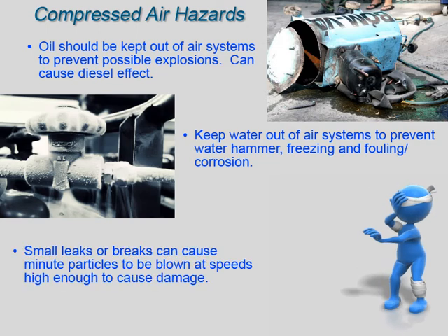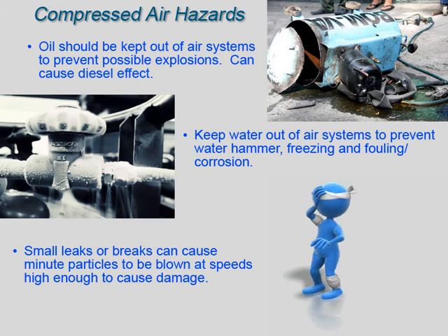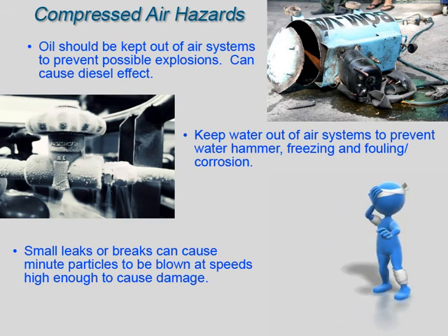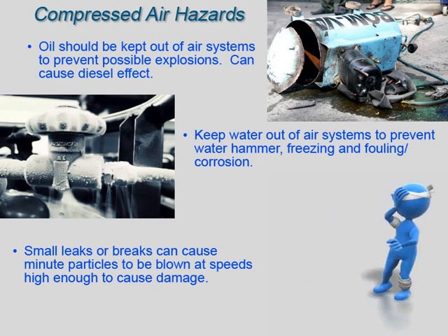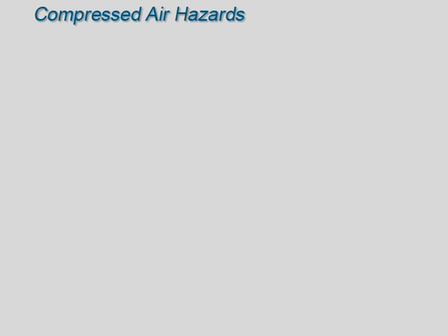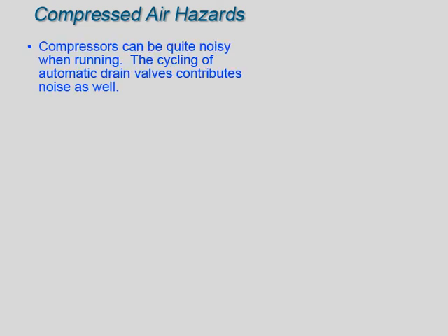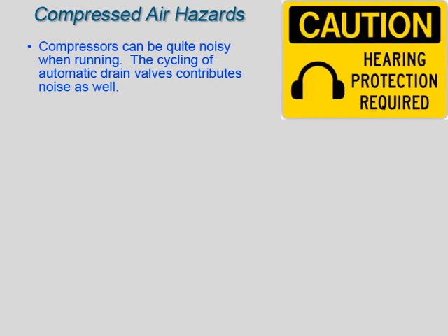Small leaks or breaks in the compressed air system can cause minute particles to be blown at extremely high speeds. Always wear appropriate PPE when working in the vicinity of any compressed air system. Compressors can make an exceptional amount of noise while running. In the vicinity of the compressor, the noise of the compressor in addition to the drain valves lifting creates enough noise to require hearing protection. The area around the compressor should normally be posted as a hearing protection zone.